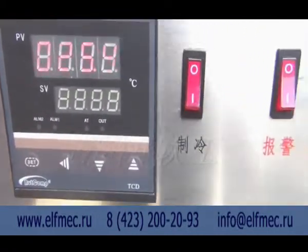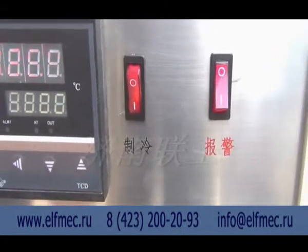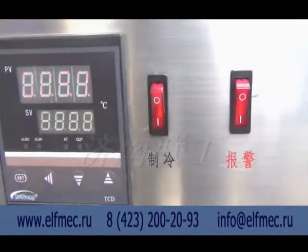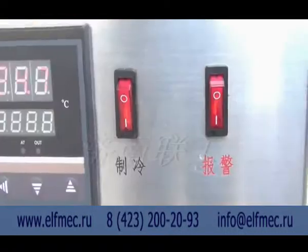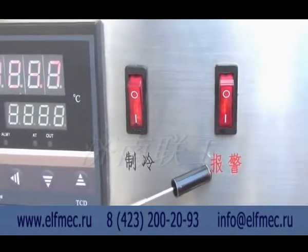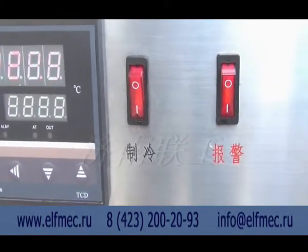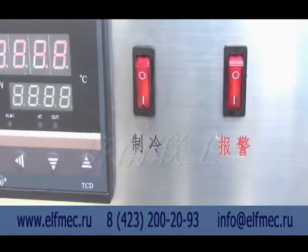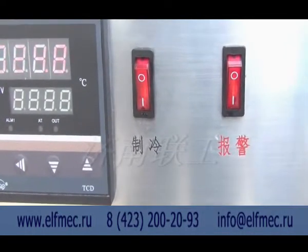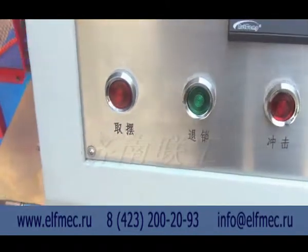Put it into the sample box. Press the Set button after setting the temperature controller to the required temperature. Make sure to open the refrigeration and open the alarm function. When the temperature alarms, keep it cooled for 10 minutes in the salt bath. Then you can do the automatic feeding and impact test.